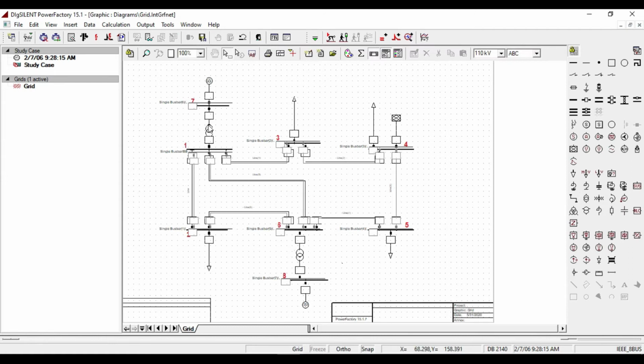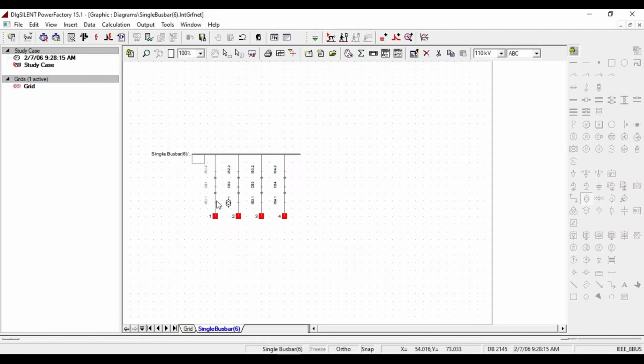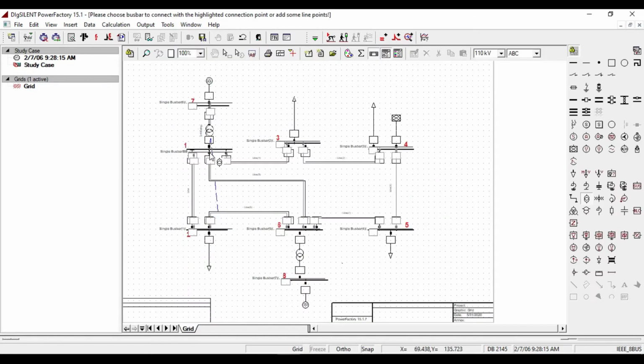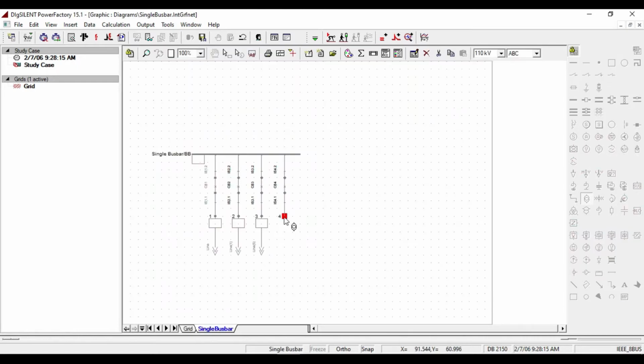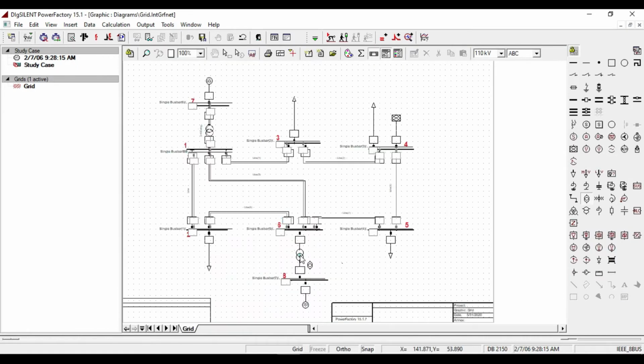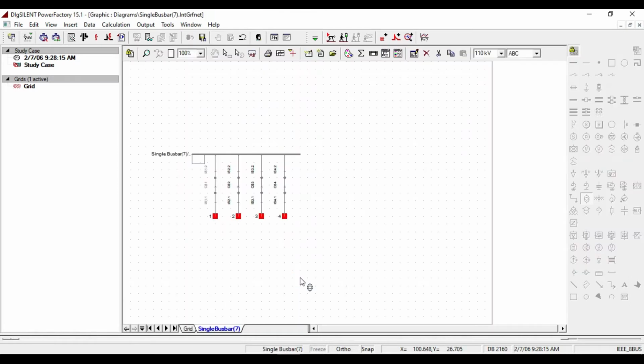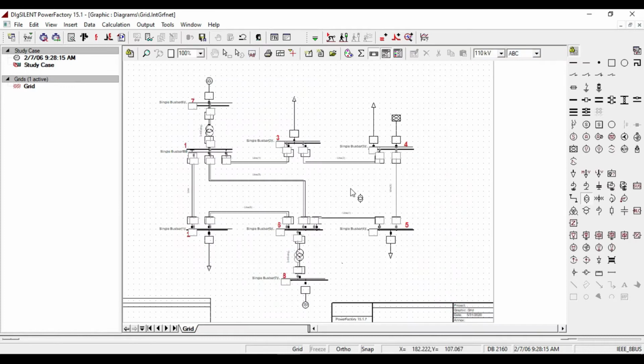There are also two transformers between this and these bus bars. Click on the two winding transformer icon, then place it to the position suggested by the background pattern. Now our bus bars are connected, then connect loads to bus bars shown by the background.